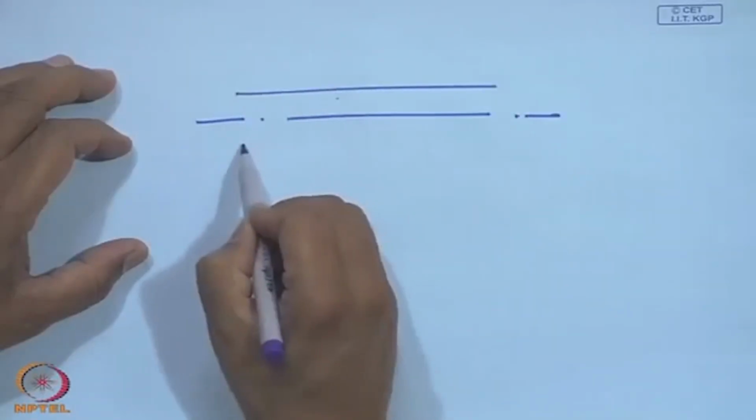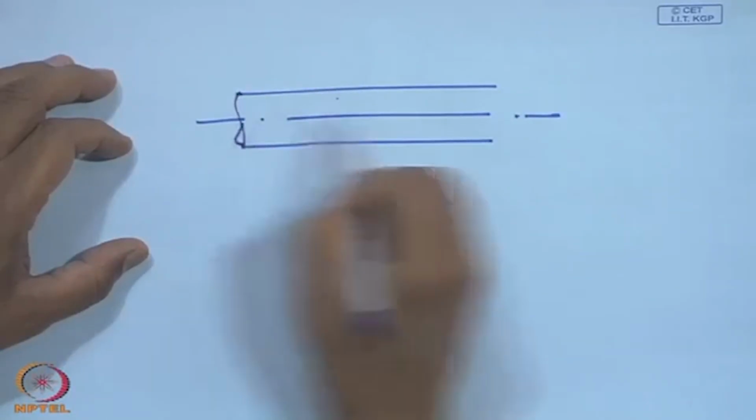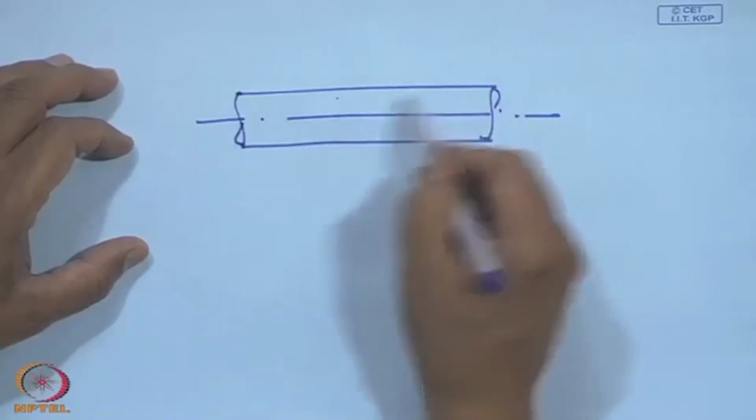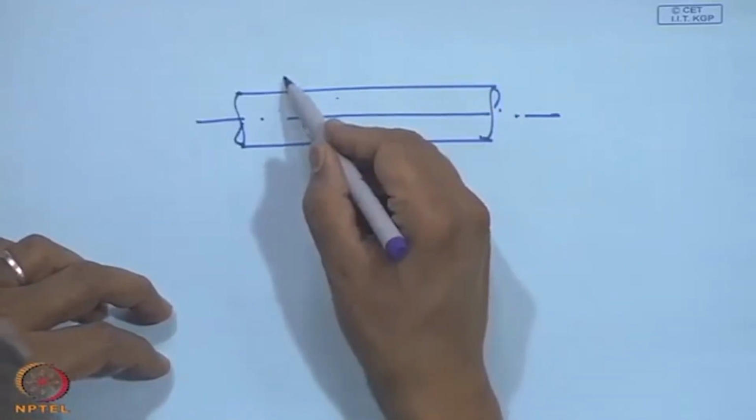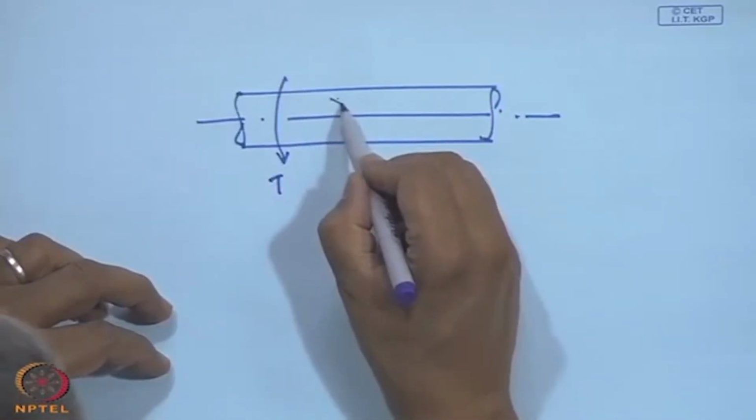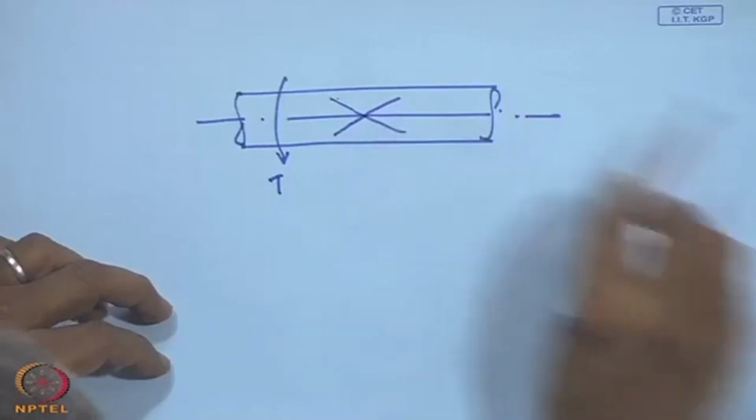Okay. This is a type of crack, which is known as the transverse crack because of the flexural loading on the shaft. Okay. Another important thing happens actually, as you know, the shafts usually carry torsional loads. They transmit power, so they carry a lot of torque. And usually, because of the torque, the maximum shear stress occurs along the 45-degree lines. Okay, if you are transmitting torque, usually the cracks are at this 45-degree axis.